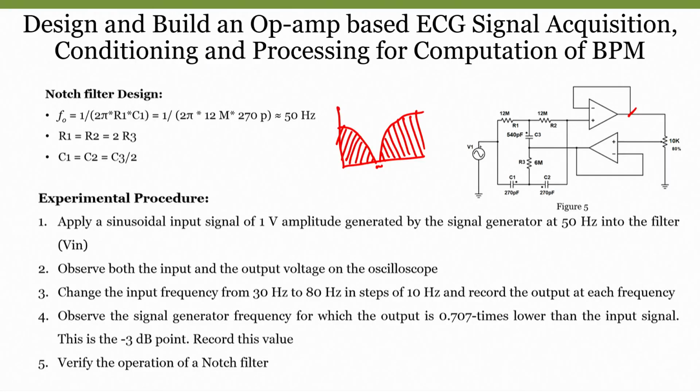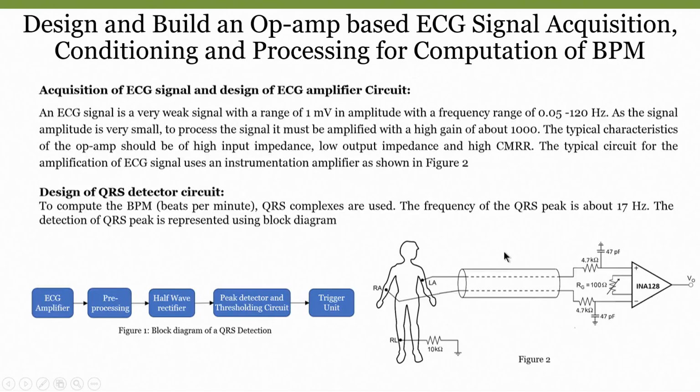Now, we will see the next step in our signal conditioning and processing unit. If we recall our block diagram, we will see the ECG amplification sometime later by the end of the experiment, and we have done the filtering part, which is nothing but a pre-processing part, which we require, especially low pass filtering, high pass filtering, as well as notch filtering. Now, next step is what?